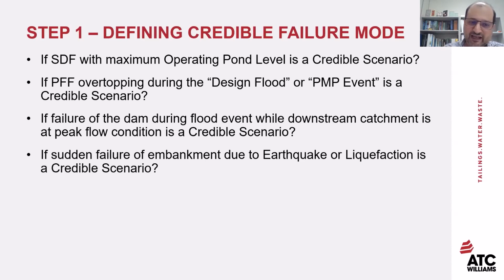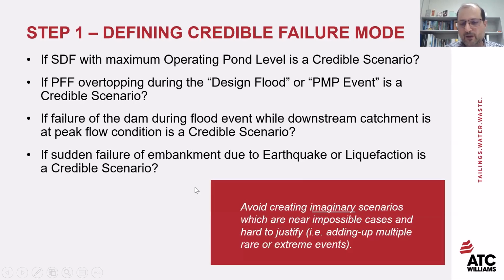We also ask if failure of the dam during a flood event, while the downstream catchment is at peak flow condition, is a credible scenario, and if sudden failure of the embankment due to earthquakes or static liquefaction is a credible scenario. What we should keep in mind is that we should always avoid creating imaginary scenarios which are near impossible and hard to justify. In other words, adding up multiple rare and extreme events on top of each other.